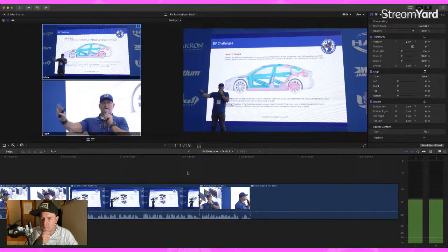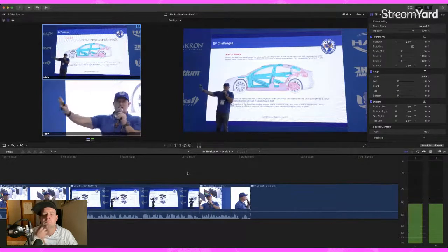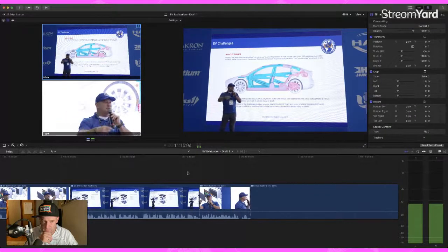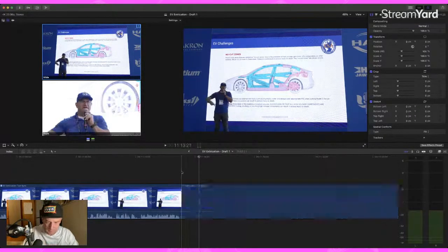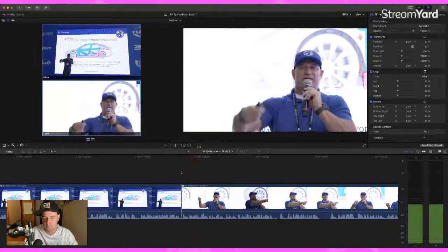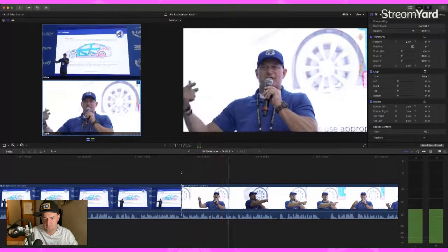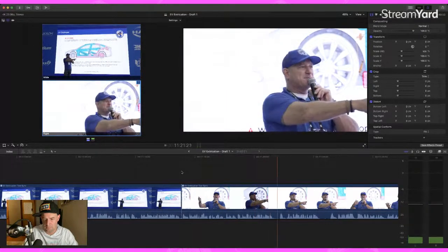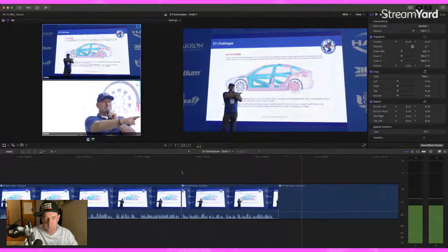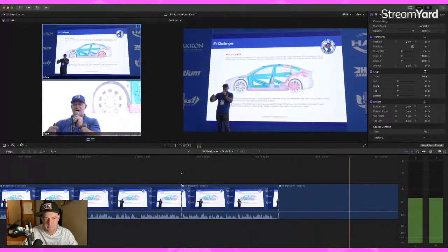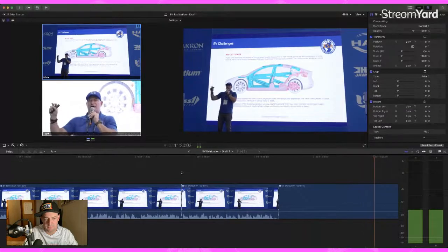So let's just talk about wheel rotation. When the vehicle is off and you move the vehicle and the wheels are rotating, that is spinning the electric motor in the opposite direction, which means it is backfeeding voltage into the high voltage battery pack. Okay? Just by show of hands, did everybody think that's going to be a problem? Yes. Okay? So when we categorize, batteries don't like electrical abuse.